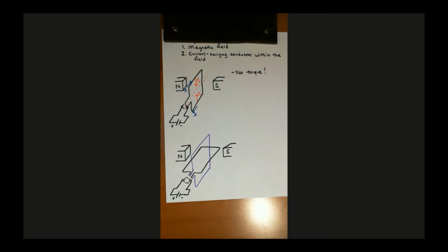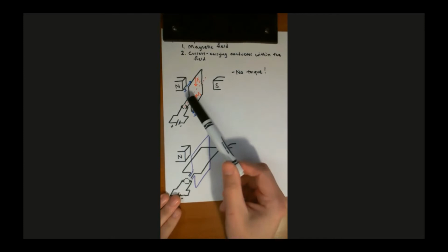So we're always going to get a Lorentz force that is aligned such that it can produce torque, and we can always have a starting torque. So we can always start the motor. All right, so in reality, you're always going to see a DC motor that has multiple coils. You'll never see a real DC motor that looks like this.